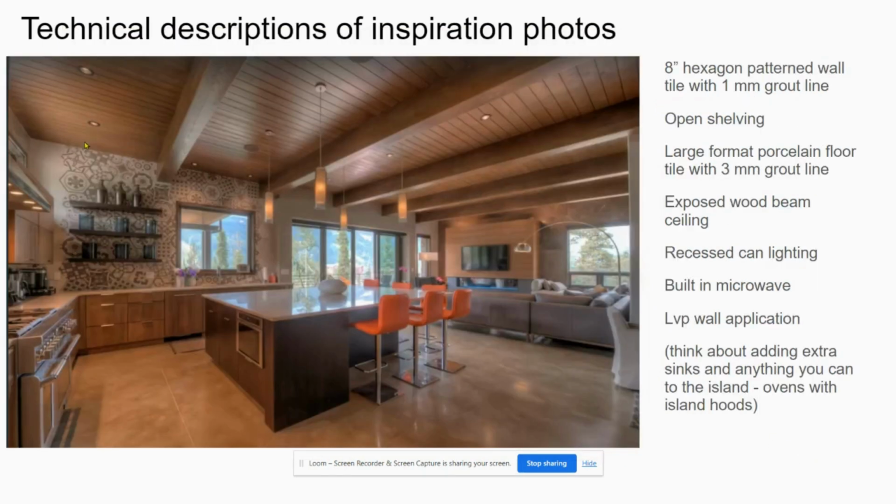All right, on the wall here for the backsplash, which they did floor to ceiling. I prefer floor to ceiling, but 18-inch is the standard. So to save money, your client might want to go with the 18-inch, but if you don't have a tight budget, it's better to do the entire wall.